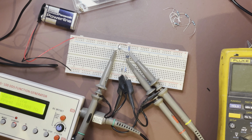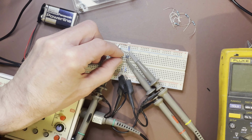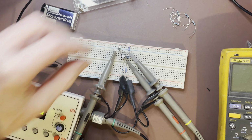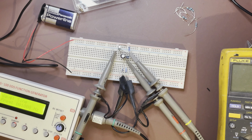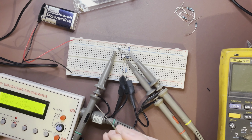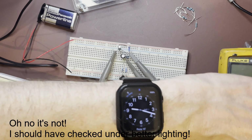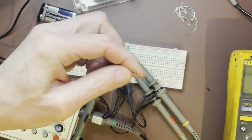So that's going to go in positive to the emitter, which is there. And then I need a 150 ohm from that to 0 volts negative. Right. So 150 ohm. Again, it's been bandoliered, so trim it, get rid of the stickiness.